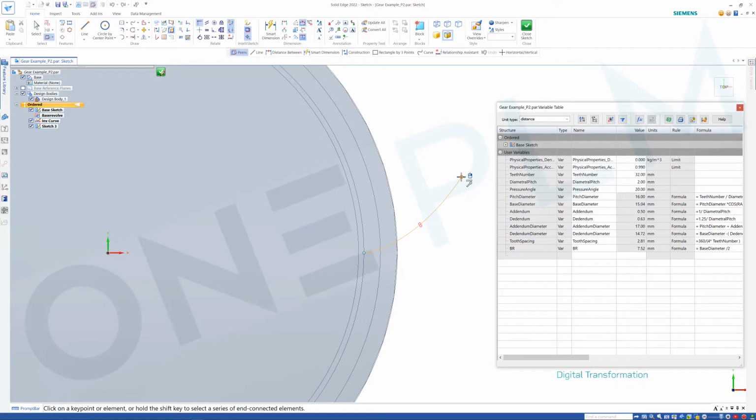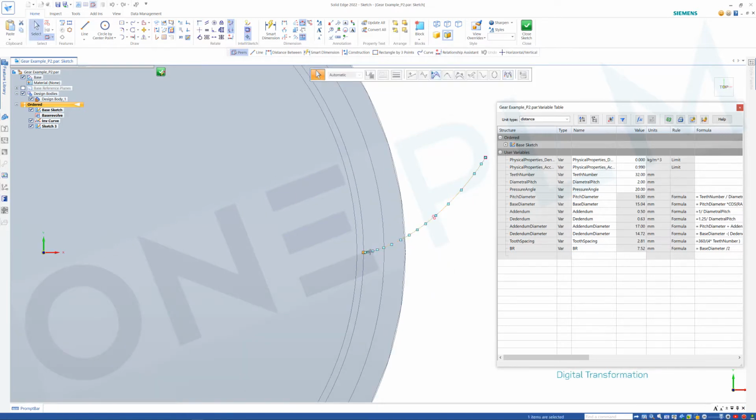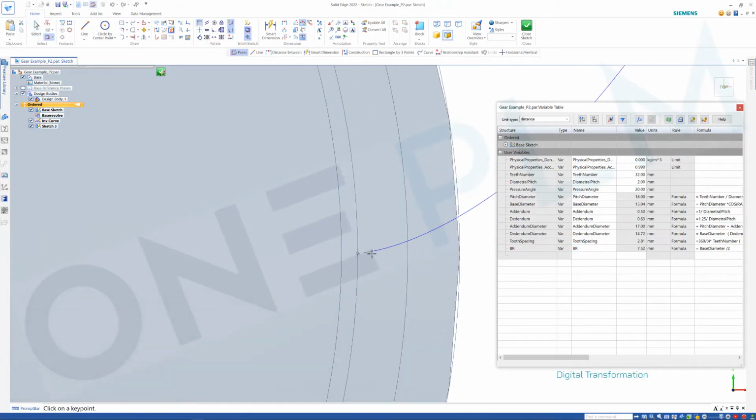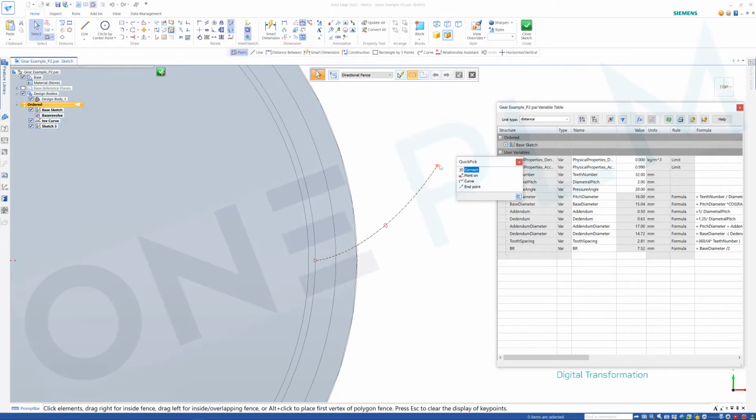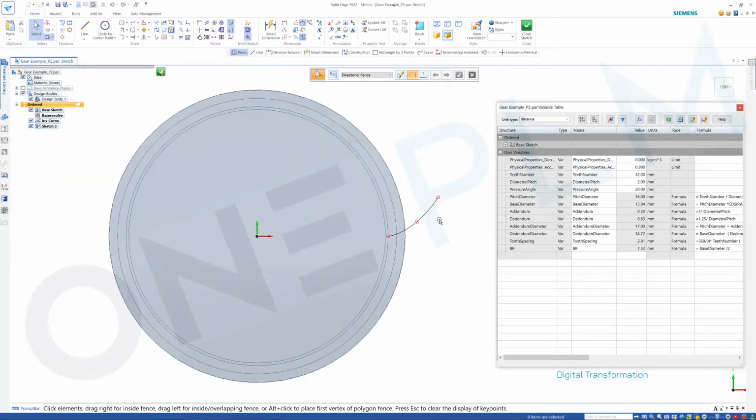And to make sure that that's also connected properly, I'm going to connect the endpoint to the endpoint underneath. If we don't do that, if we click on that line, notice that's going to drag down. So by using that connect we can connect that to the endpoint, and then that to the endpoint on there, and it should then go fully defined. If it doesn't connect, just drag it across and then reconnect it using the connect button to make sure that it becomes fully defined. Okay, so we should end up with our little link symbol, our square endpoint connect. If you do get any other ones, just use the quick pick option to make sure that we haven't got any of those other options that we don't want.